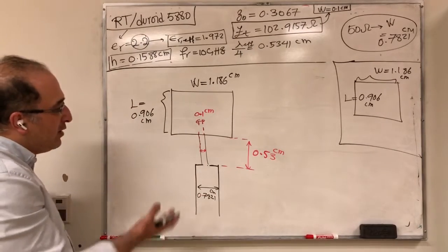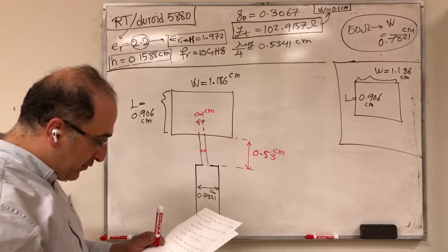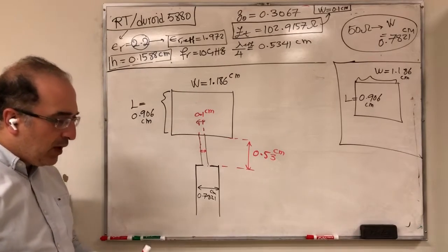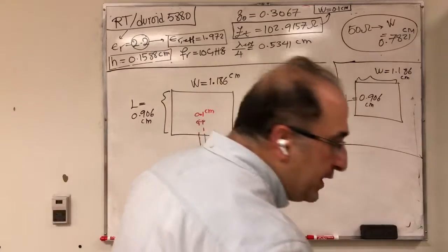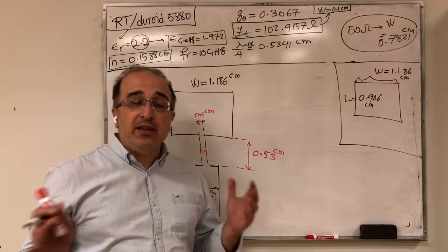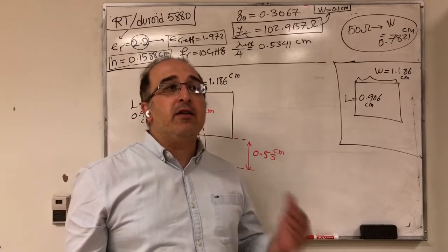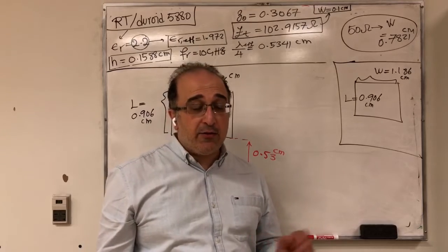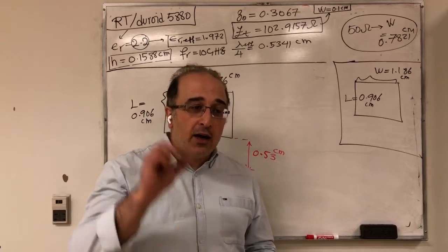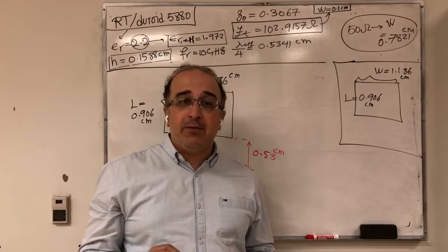So as you see now, we have the complete package for quarter wavelength transformer. So that would be the end of quarter wavelength transformer. So in summary, we learned 3 techniques for feeding the patch. One of them was inset feed. The other one was probe feed, the first 2. And both inset feed and probe feed work based on the idea that you go a little bit inside the patch and you feed it at that point.